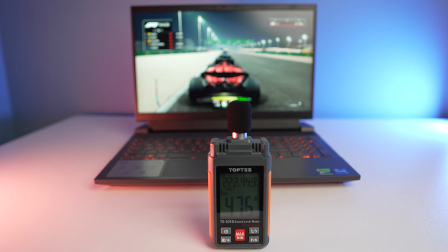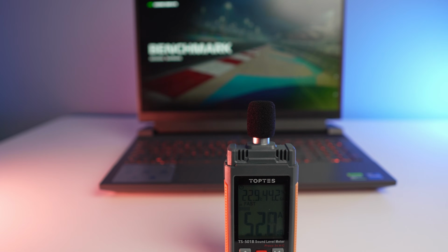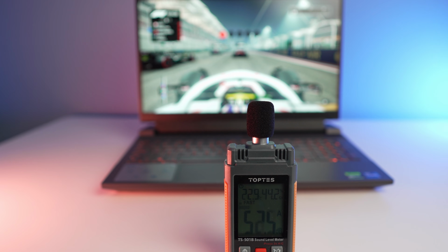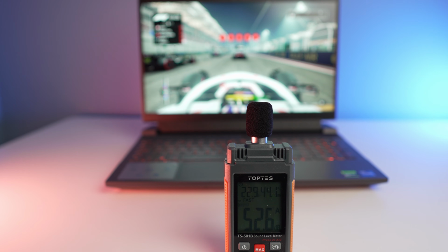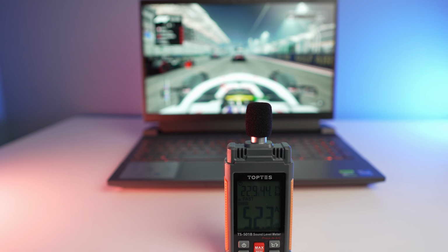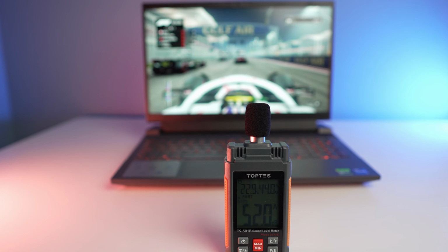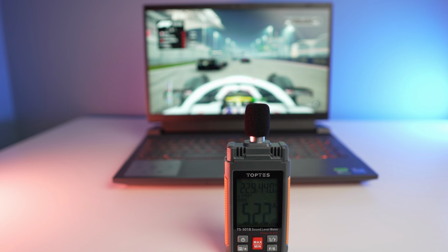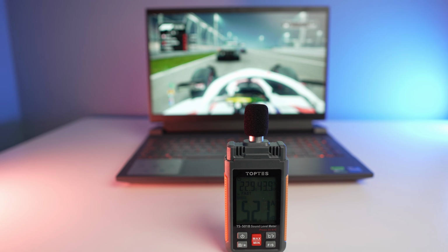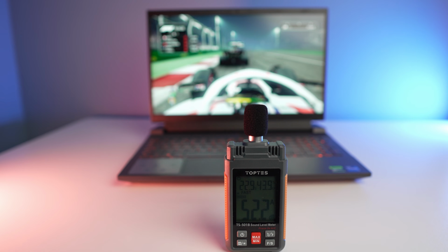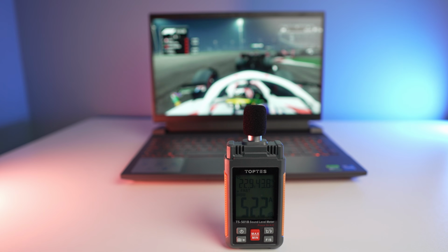As we move from that into the custom mode, this is with the custom fans turned all the way up. We've got 100% CPU fan and 100% GPU fan with the CPU undervolt applied, TCC clamped to 85 degrees Celsius on the CPU, as well as the CPU limited to 4500 megahertz as a max turbo boost speed. We've got about 52 decibels running in custom mode with these custom settings applied with QHD resolution. Not a bad showing, but not something that you'd want to play with at all times either.